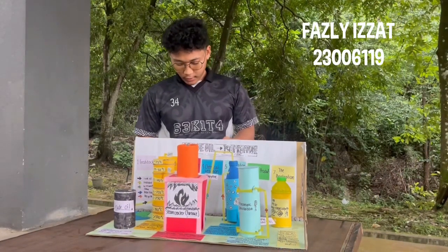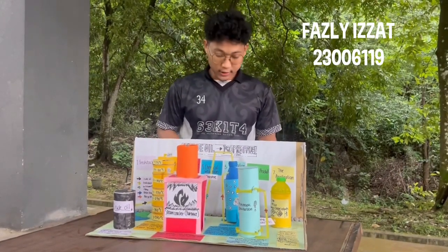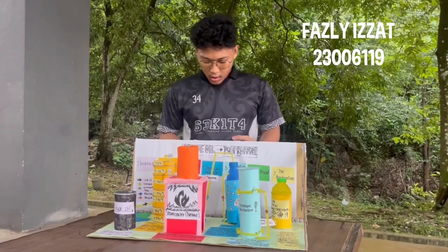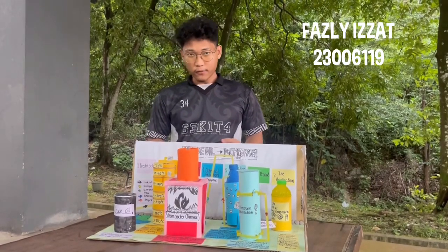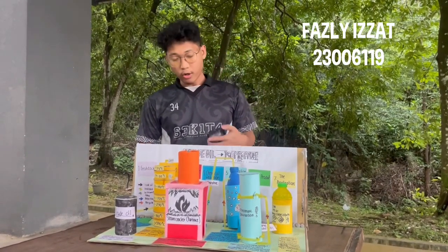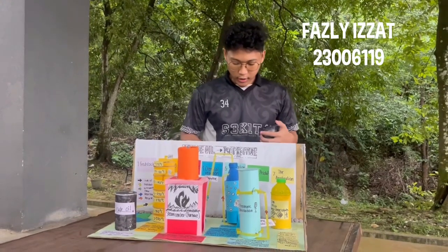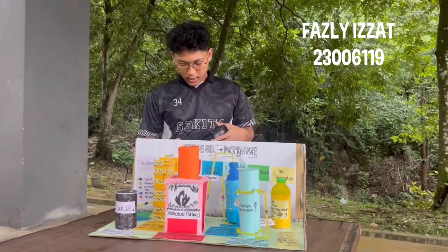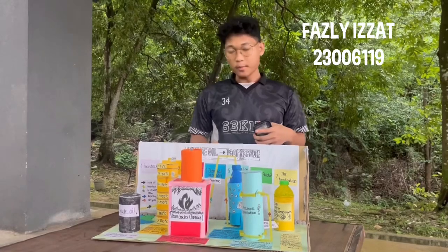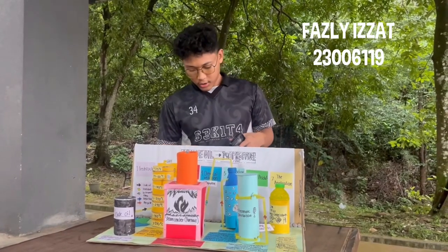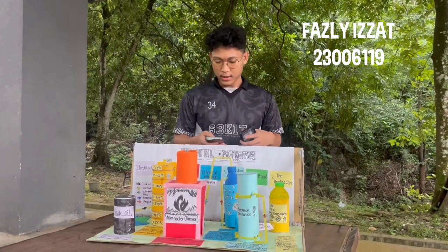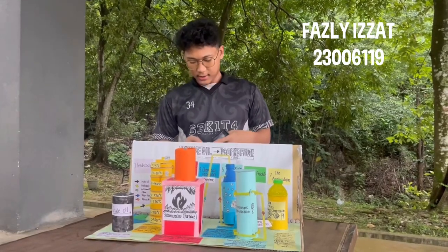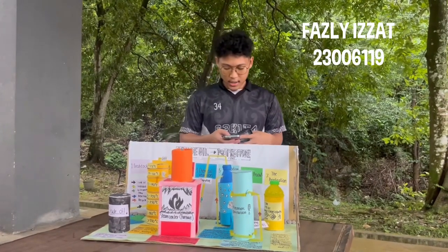Moving into topic 7, we receive the crude distillate from the hydration stage. While distillation is our primary tool for separation based on boiling points, ordinary fractional distillation alone cannot completely purify the stream. This is because isopropanol and water form a minimum boiling homogeneous azeotrope at approximately 80 Celsius, where the liquid and vapor compositions become identical.